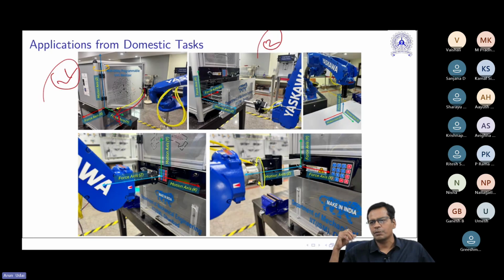So in earlier days, people used to have the end effector fitted on a spring-like structure. Any uncertainties were taken up by such a structure. Writing on a board, you have already seen, and pushing a button. Again, you need to create a normal reaction against that, and you are free to move along the remaining two directions, right? Again, rotating a knob switch, right? You can rotate about this but cannot rotate about the other two axes.